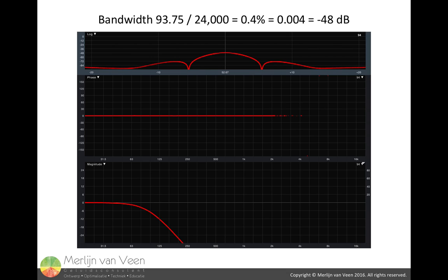By the time we get to 94 Hz, we are left with 1/256th of the initial information, and the amplitude has dropped to minus 48 decibels. There is less than 0.5% of the initial information for the analyzer to work with. One way of offsetting this progression would be by raising the output level by 6 dB for each octave in bandwidth reduction accordingly. But with ultimately 48 decibels of loss to compensate, there is limited merit to this solution.